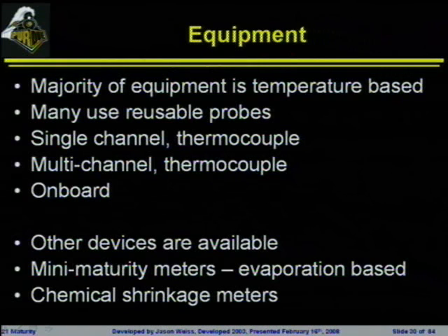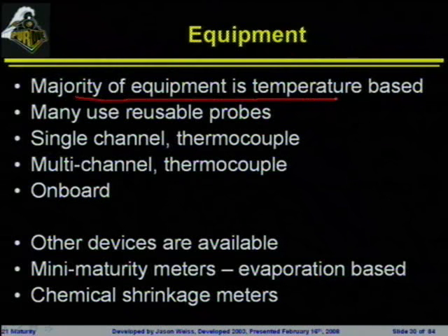Okay, so the majority of equipment that's out there is temperature-based. Now, I will show you one or two systems that are not temperature-based, but by and large, other than a few oddballs, people who spend a lot of time getting really excited about maturity, like myself, most people, when they say maturity, are talking about temperature. They're talking about measuring temperature. They're talking about the time-temperature relationship.